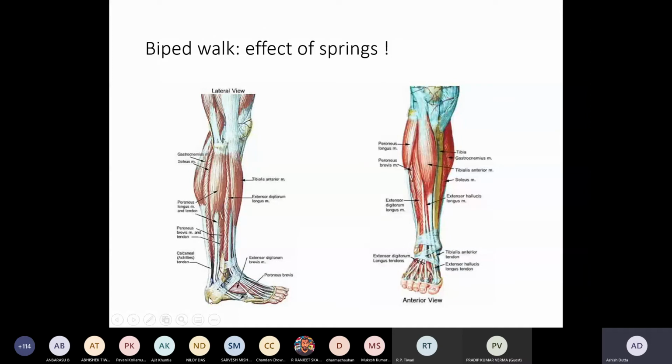But then the way the biological systems are actuated, we have a muscle, and then a tendon, and the tendon is connecting to the joint. So the hands or the legs are not directly actuated by the muscles. The muscles indirectly actuate the joints by means of tendons, and these tendons have some kind of stiffness. Okay, so they are elastic, they behave like springs.